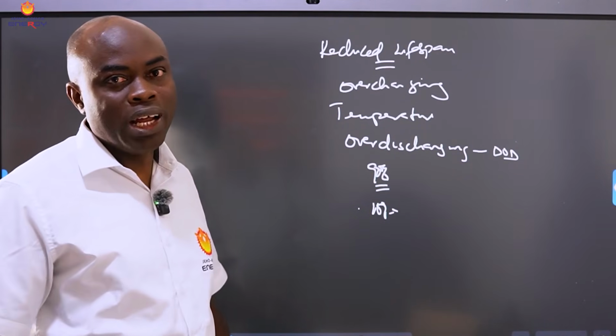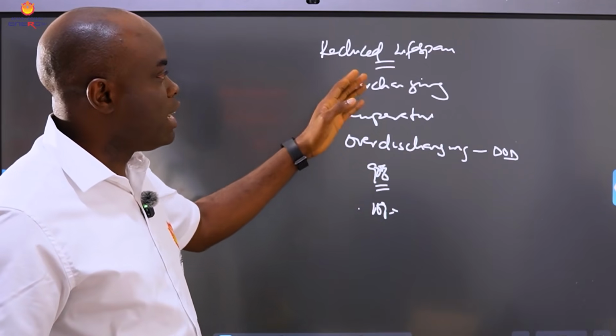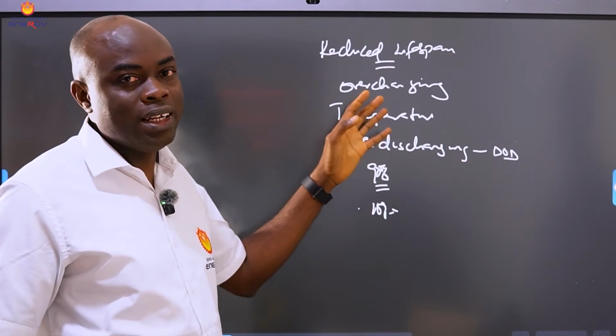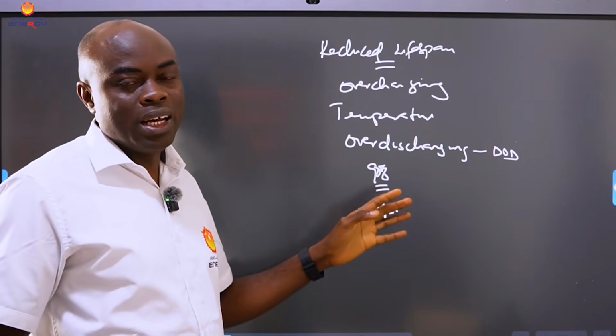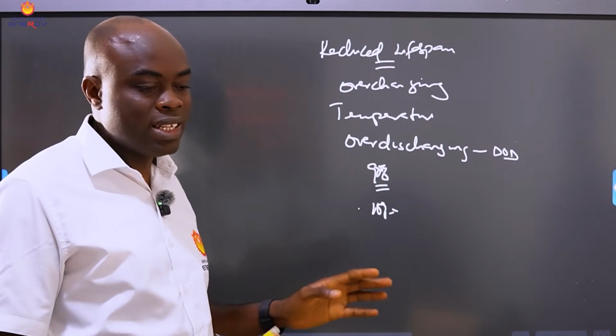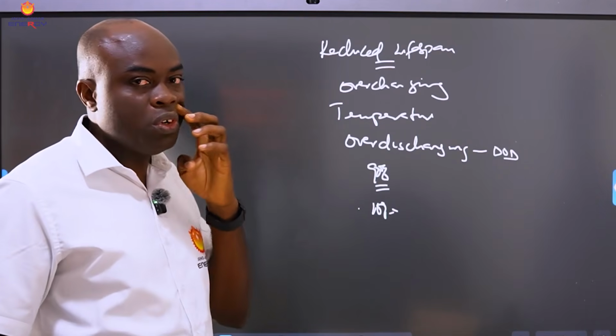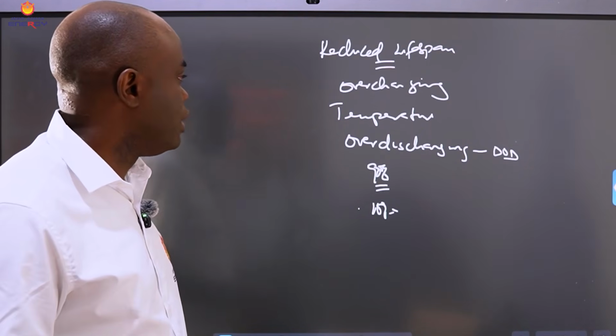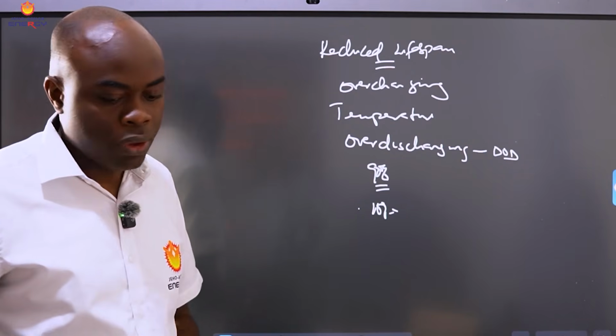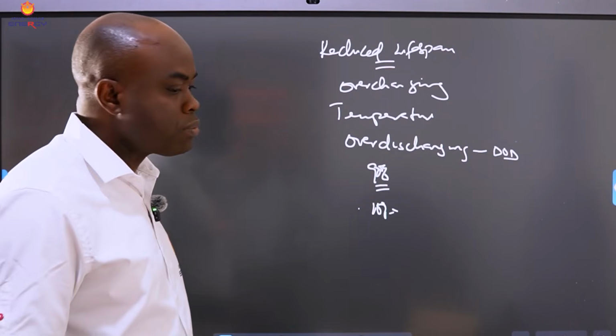So if you are a home user, a C and I user of solar energy system, it's very important to ask your installer about the CAN RS485 communication cable between your systems. Are they properly installed and set for communication between your battery and the inverter? Because you are mindful of the lifespan of your battery and the inverter.